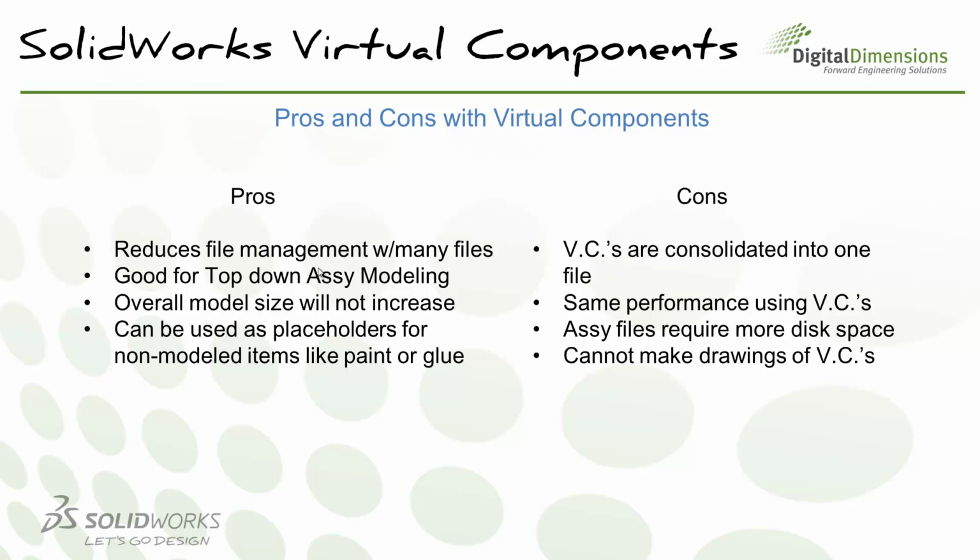The last con with working with virtual components is the fact that you cannot make drawings out of these virtual components. I did explain that you can save these virtual components as separate items externally, so you can do that and it becomes a fully fledged part file, so you can make detailed drawings out of them.